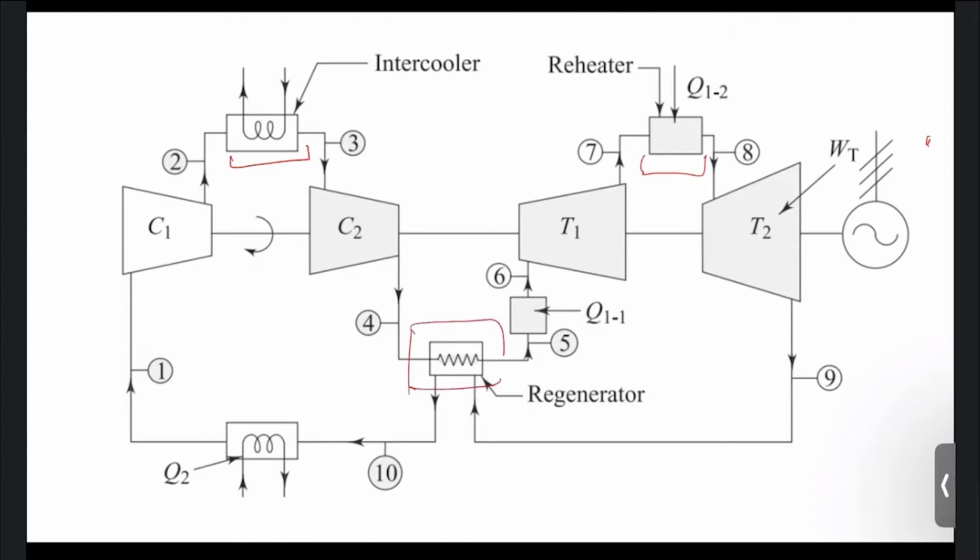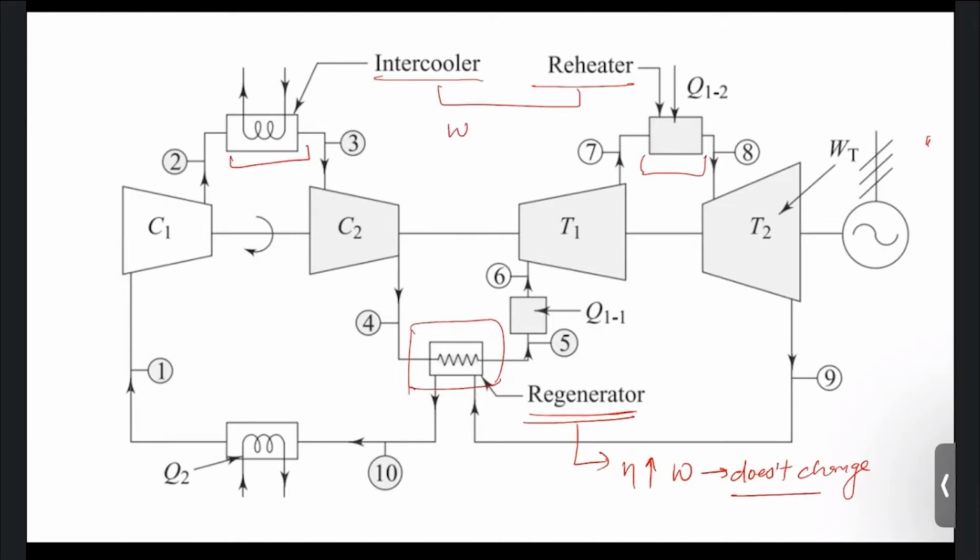Okay, so in the case of regenerator, efficiency always increases, but work done doesn't change. So there is no change in work done, but efficiency always increases with the use of regenerator. But in the case of intercooler and reheater, in both the cases, work always increases and efficiency always decreases.